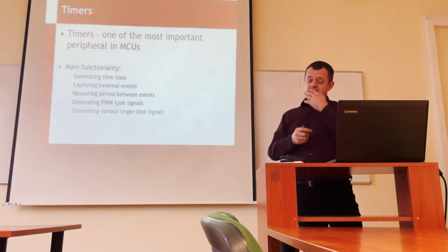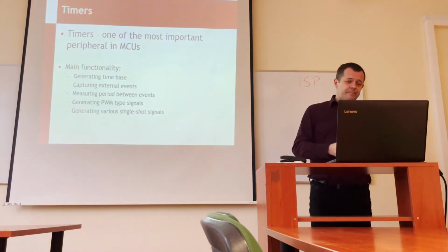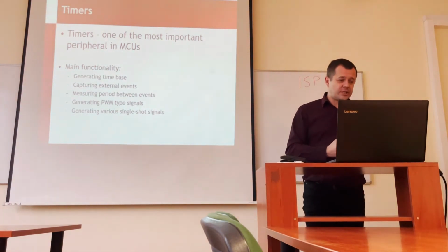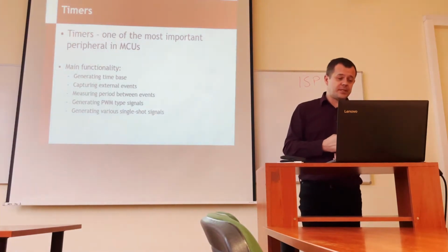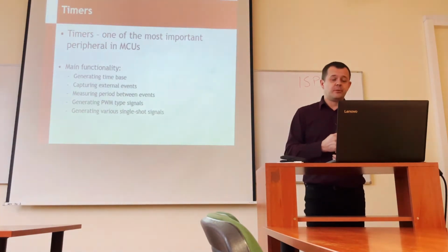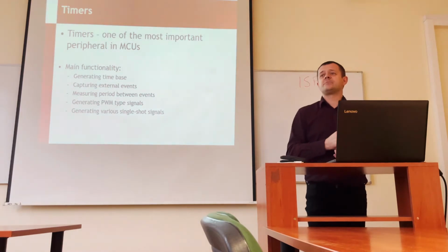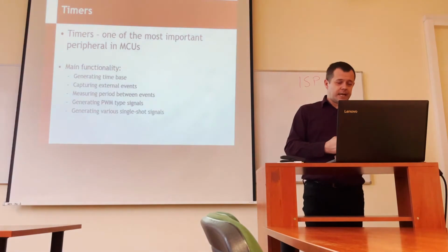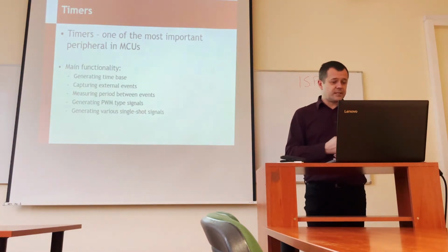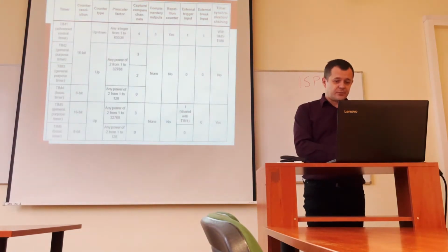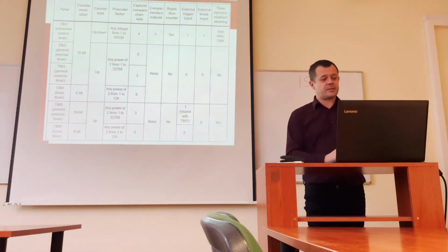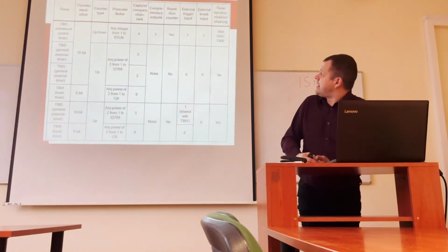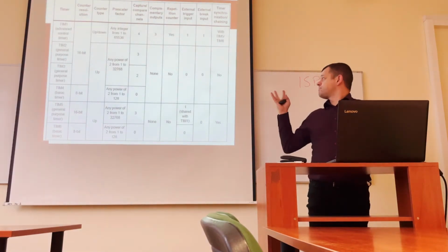We can measure the period between events, so it's very much connected, but still a bit different functionality. We can generate PWM signals, so PWM is of course pulse width modulated signals, but also PDM signals, pulse density modulation, we can generate. And various single-shot signals we can generate here as well.